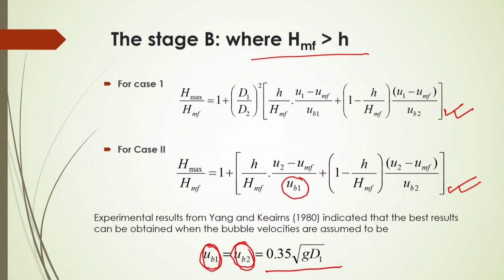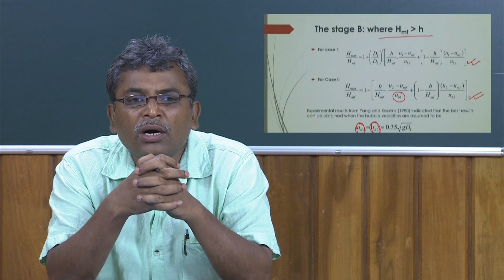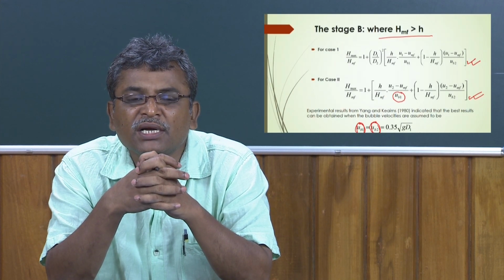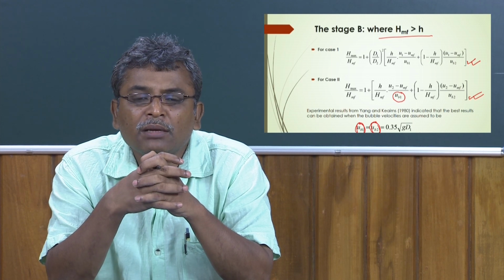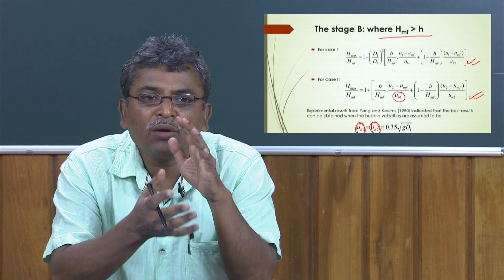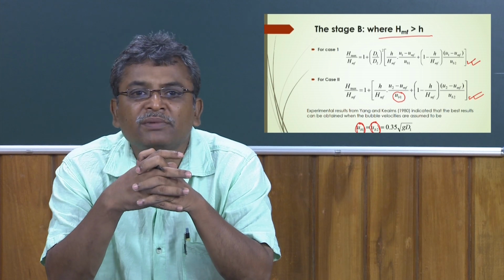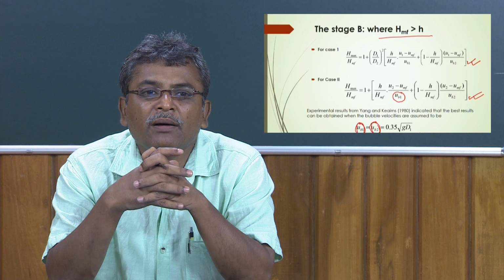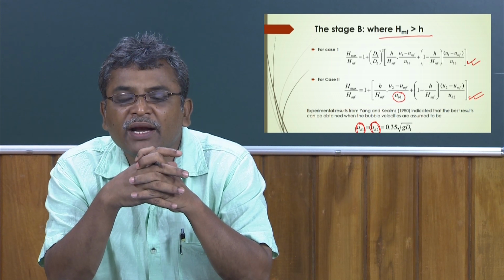And so, in this lecture we have observed how a bubble forms, and how bubbles make a slug if there is coalescence; bigger bubbles make longer ones, and there are different shapes of these longer bubbles. One is nose shaped, one is elongated, and another is flat shaped.